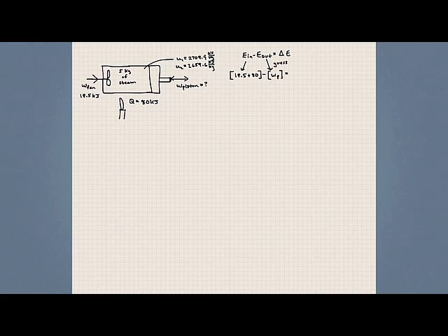And the change in energy of a system, keep in mind from our lectures, is going to be the sum of the change in internal energy at the two states, the change in kinetic energy, and the change in potential energy. Well, since this system is not moving, it's fixed, we can neglect our kinetic energy term.